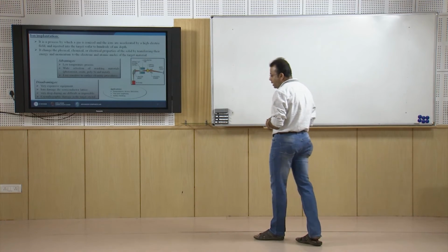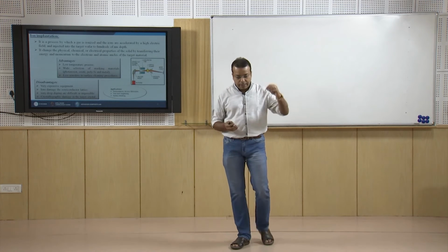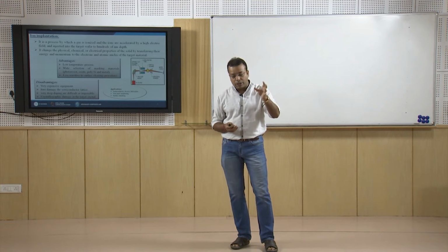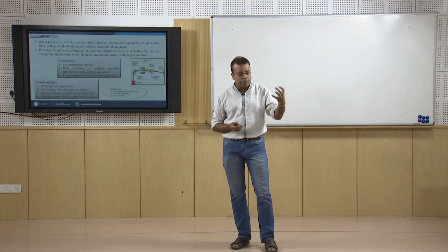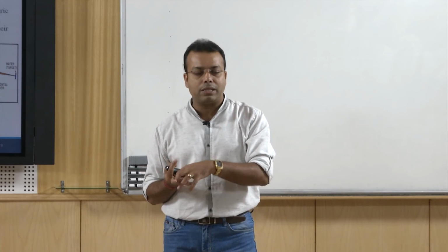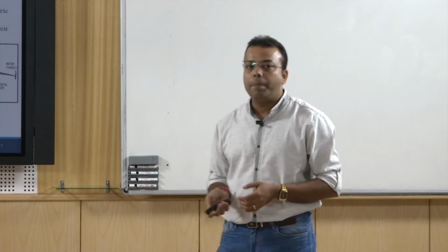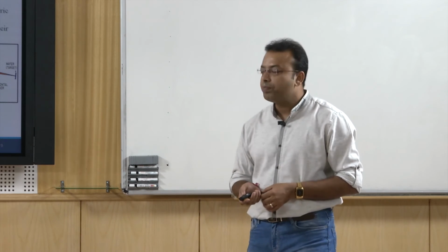Next one is called ion implantation. So, ion implantation means we have some substrate, then we use a certain kind of electron gun or some kind of ion source, and we agitate those materials. Then from that target, ions come and fall directly onto your base metal, then they react or go to the interstitial sites, and by this you do the modifications.